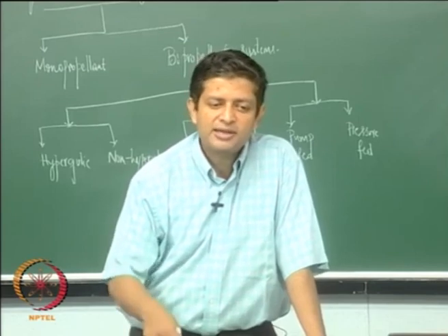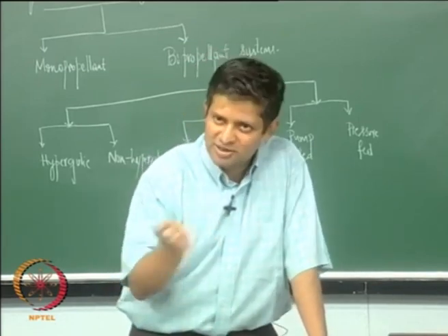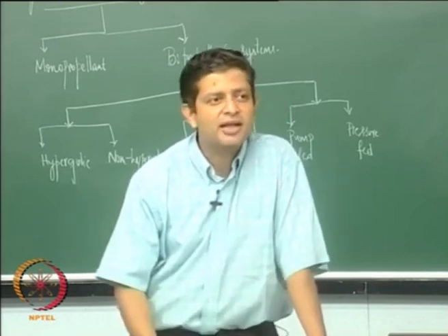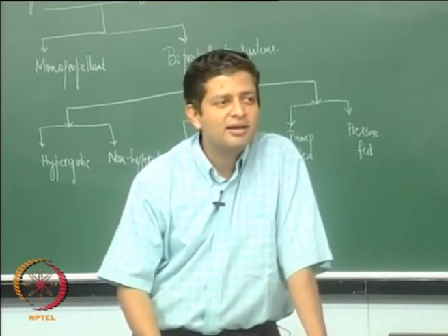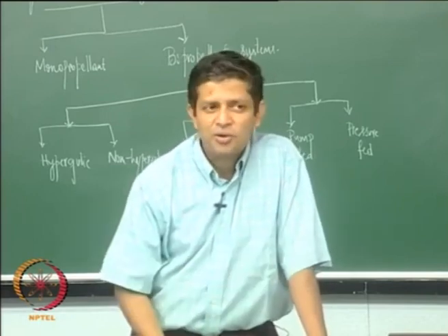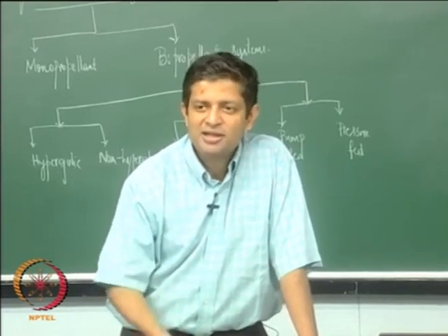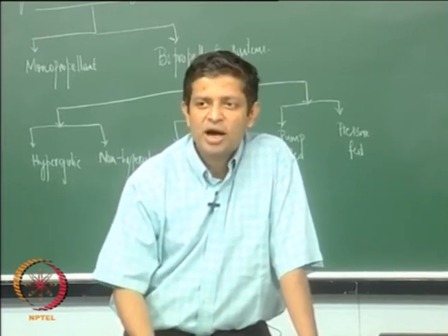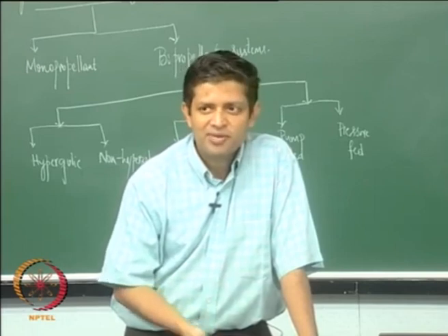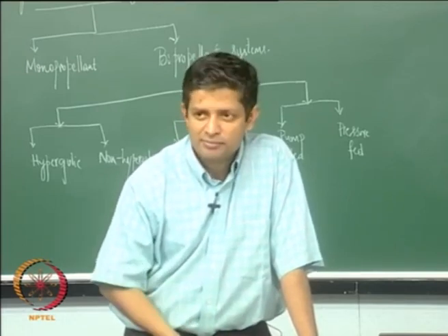The good thing about these electrical thrusters is they have very low thrust, which is what is needed for this operation, but their ISPs are typically 2 orders of magnitude more than what is seen here. So therefore your operation time will increase if you have a higher ISP. So that is the direction in which people are moving.